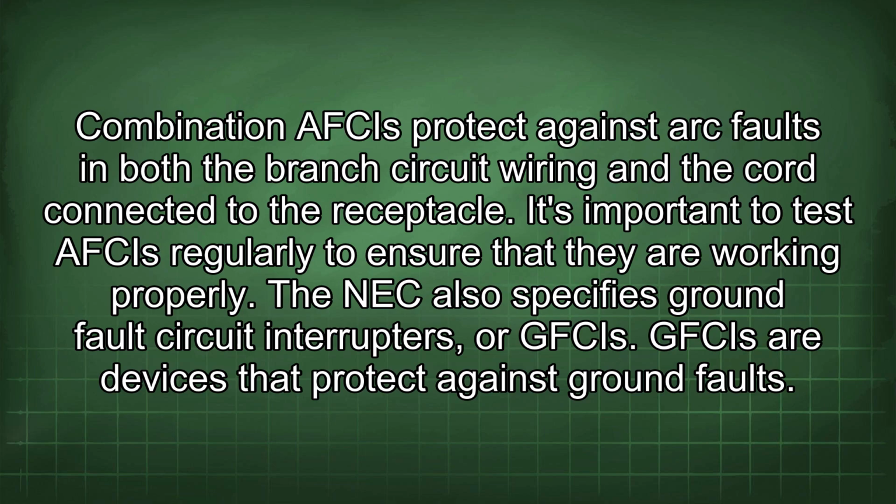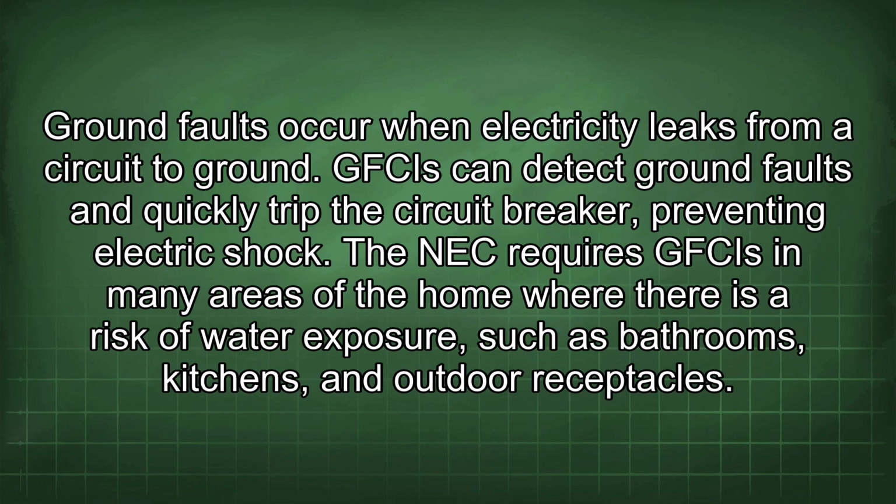The NEC also specifies ground fault circuit interrupters, or GFCIs. GFCIs are devices that protect against ground faults. Ground faults occur when electricity leaks from a circuit to ground. GFCIs can detect ground faults and quickly trip the circuit breaker, preventing electric shock. The NEC requires GFCIs in many areas of the home where there is a risk of water exposure, such as bathrooms, kitchens, and outdoor receptacles.